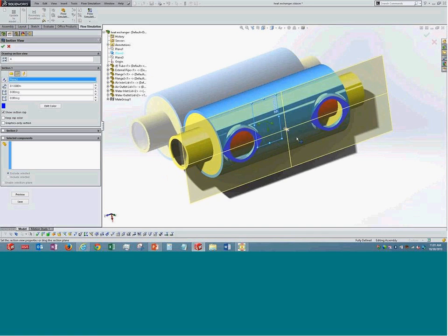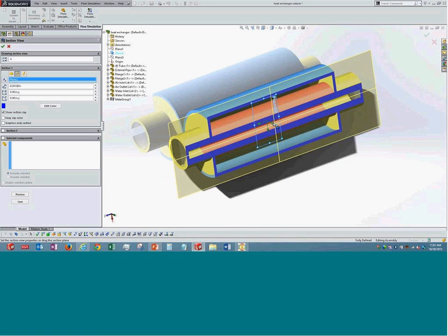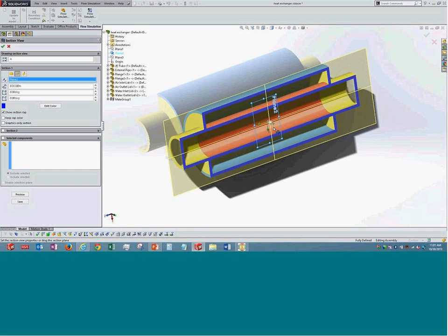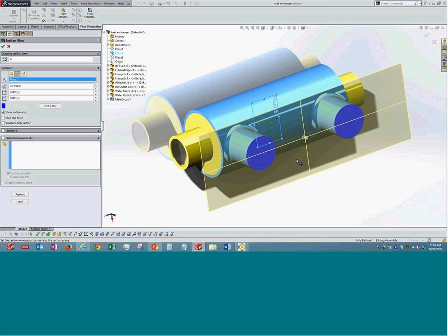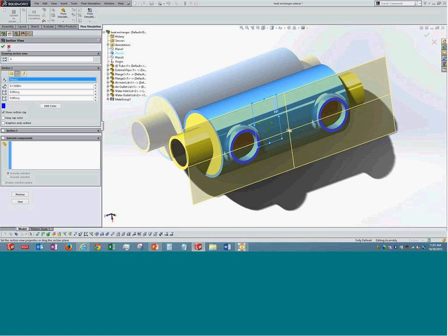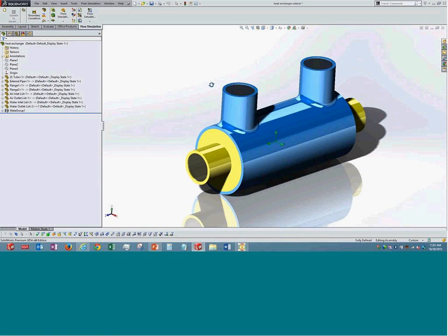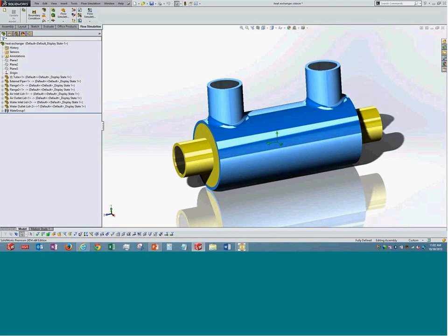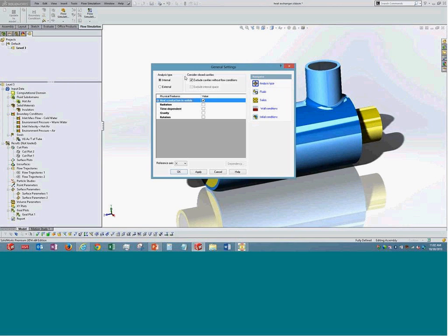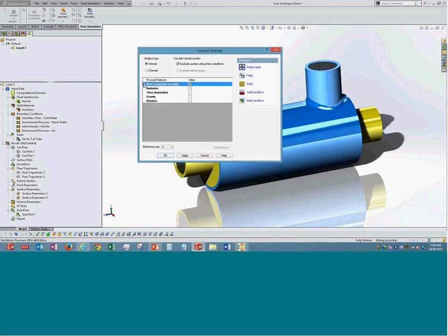Now here, as I told, it is a heat exchanger. One thing is that we are simulating heat. So I'm selecting this option of heat conduction in solids. So this option is selected, so we are simulating heat. Second, fluids. We are selecting two fluids over here. It is not one but two. One is air, the second one is gas. So we are selecting two fluids. One thing is I'm just heating the gas, liquid or other.